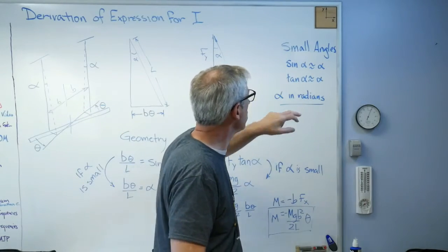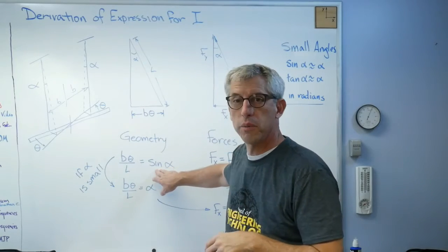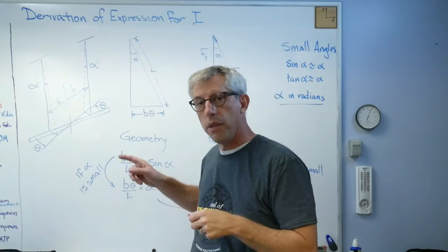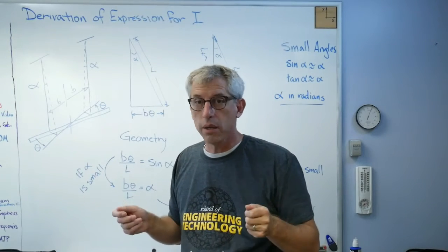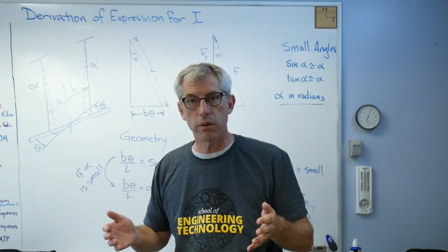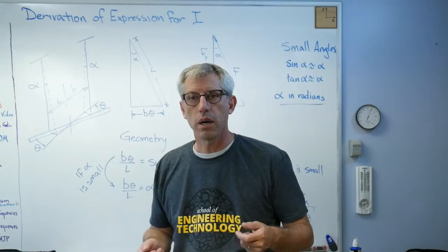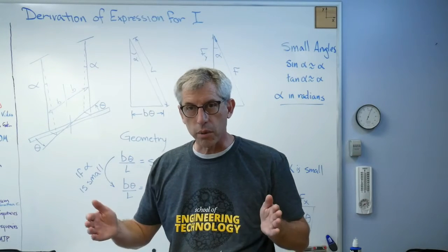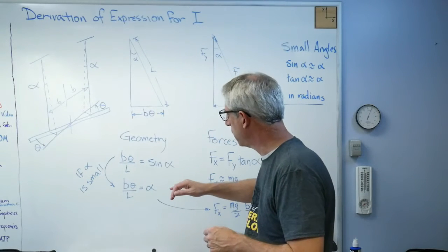What this does is make it so that some of these nonlinear terms go away, right? This only works if you're only swinging through a small angle, okay? A couple of degrees, right? The expression I'm going to derive for you does not work if you have like a 45-degree angle on the bifilar pendulum. It's just a very small deformation or displacement.